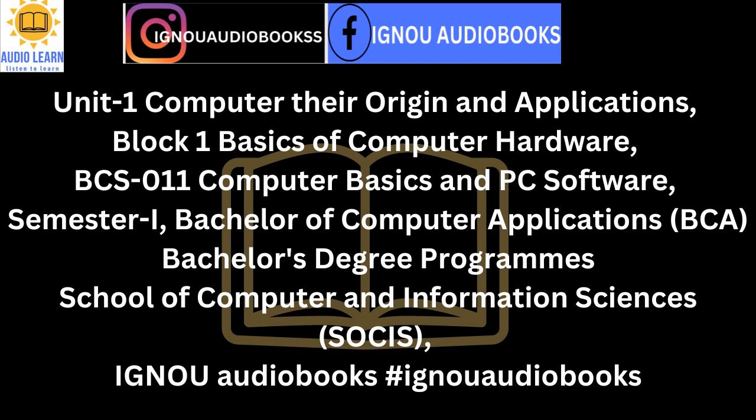1.5.1 Electronic circuits. The integrated circuit is nothing more than a very advanced electric circuit. An electric circuit is made from different electrical components such as transistors, resistors, capacitors and diodes, which are connected to each other in different ways. It is an unbroken loop of conductive material that allows electrons to flow continuously. If a circuit is broken, its conductive elements will no longer form a complete path and continuous electron flow cannot occur. The transistor acts like a switch.